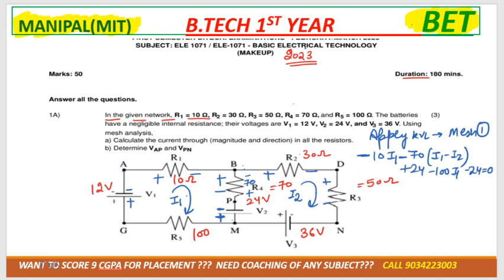So this is your first mesh equation. Similarly, we can calculate the second mesh equation. That would be minus 30 I2 minus 50 I2 plus 36 minus 24 minus 70 (I2 minus I1) is equal to 0. Correct? Okay. So this is the second equation and the first equation. You can solve both equations and you'll get the values for I1 and I2.